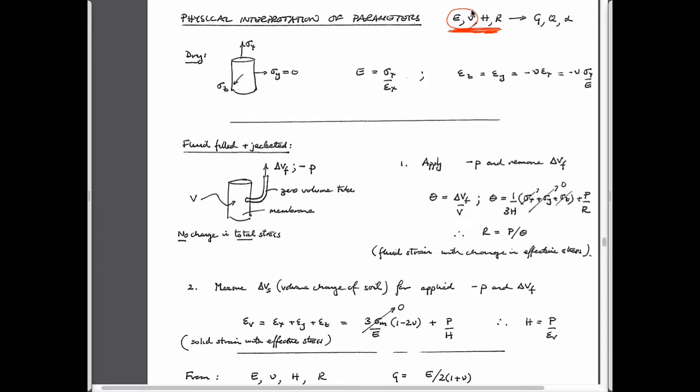These are the four basic parameters that we need to define the system. Modulus and Poisson ratio together are embodied in the shear modulus, so those reduce to one. And these coefficients H and R, which are actually measurable properties, are typically translated into these other components, Q and alpha. Sounds complicated, but let's go for at least a physical understanding of what's going on.